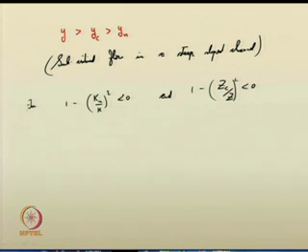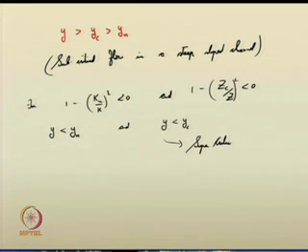For this criteria, you can suggest that your depth of flow should be less than normal depth as well as less than critical depth. So, this means that supercritical flow has to exist, then only you will get the backwater curve.